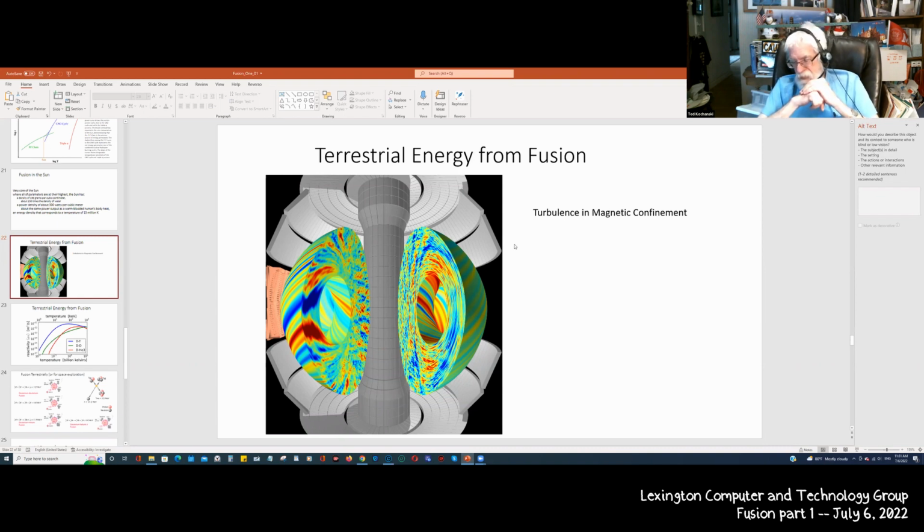And there's some predictions that you might knock every iron atom, if it's stainless steel, essentially every iron atom would be knocked out of its place in the lattice once a month. Now, how long can that go on before you have to replace it, or you have to anneal it, or something else that you have to shut your equipment down to do it? Nobody really knows yet. That's kind of the engineering stuff that still needs to be really looked at.